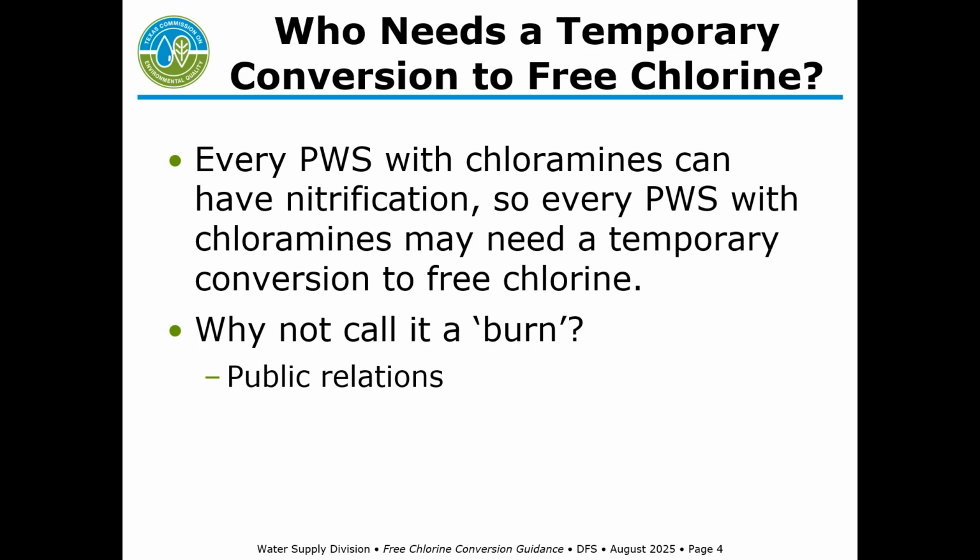So any PWS that is using chloramines can have nitrification in its distribution system. So this could apply to any of those systems. So why don't we at the TCEQ call it a burn? Well, for really two reasons. Conversion is more accurate. We're not actually burning anything, and it doesn't sound so positive to your customers to tell them that you're burning their water. So if you don't like free chlorine conversion, I've heard people say something like free chlorine refresh, but we're just trying to get away from the term burn.